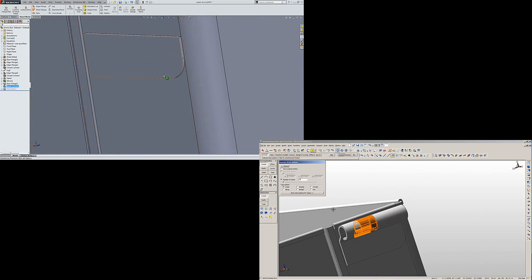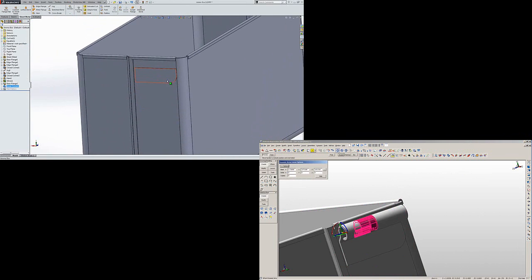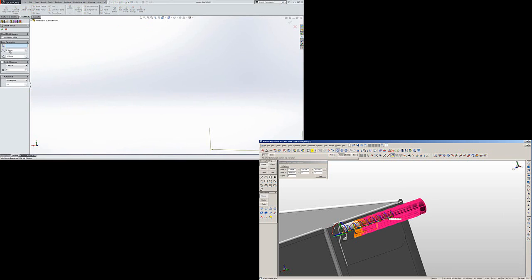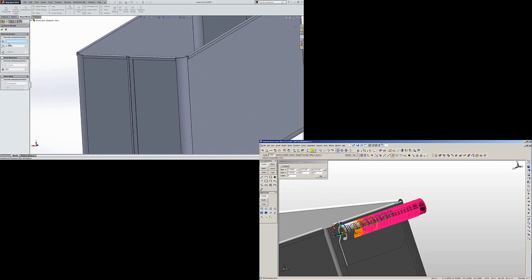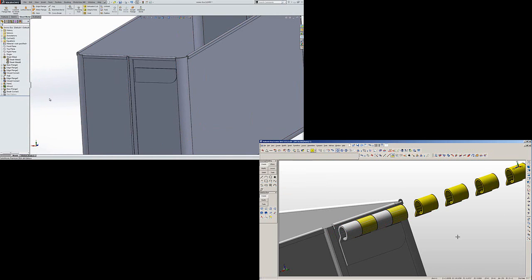That's a nice little feature you can do with the corners. So next we're going to create our hinge. What I'm going to do is double check that our internal radius is 1.5, which is correct, and that's going to be for all multi-bodies here. Now we can go into the multi-body and edit it if we want. We can overwrite it for that multi-body, but it's right now, so we'll okay that.